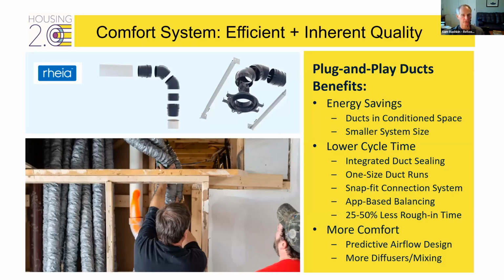I should mention that there's amazing game-changing technology, plug-and-play ducts. Aeroseal's RIA is the first manufacturer. It takes the installer out of the equation, both for design, installation, and for airtightness of the ducts. They snap in airtight, and they're dedicated runs from a kind of a mixing box at the top of the plenum, where you have dedicated lines to each room. They're all the same size, so the number of lines to each room is all pegged to the CFM flow requirements you need by the design.